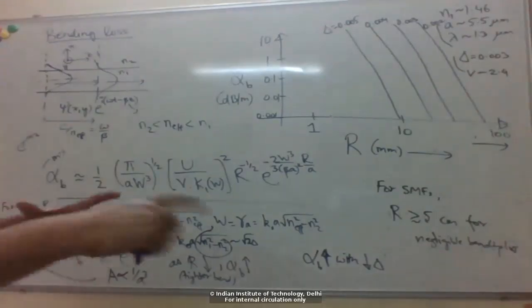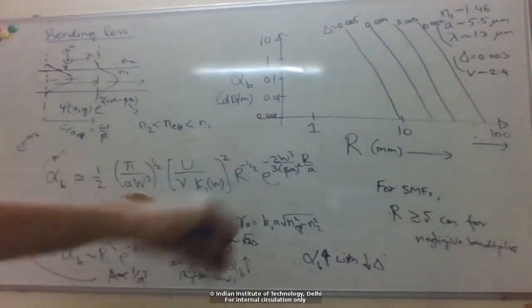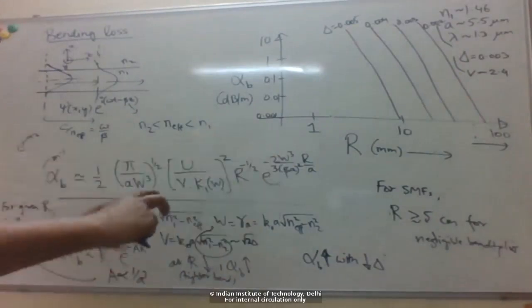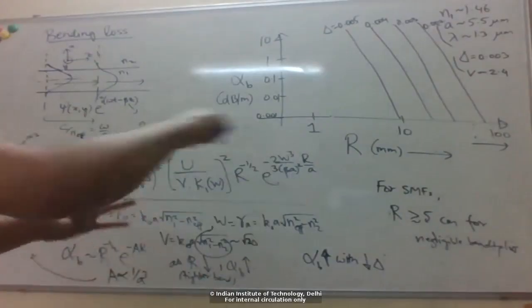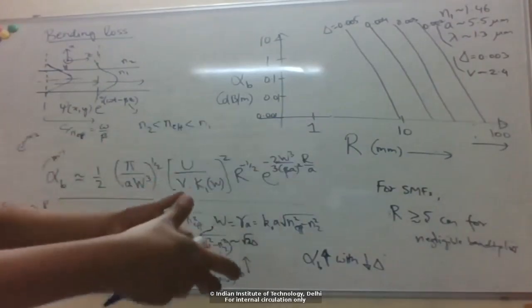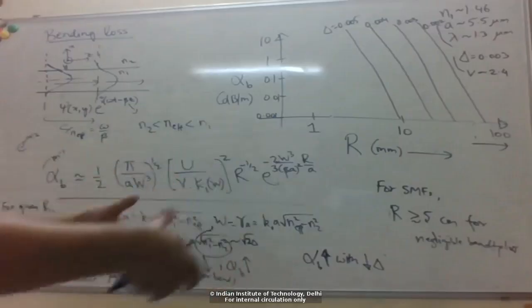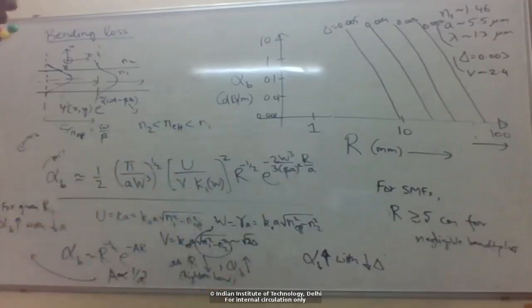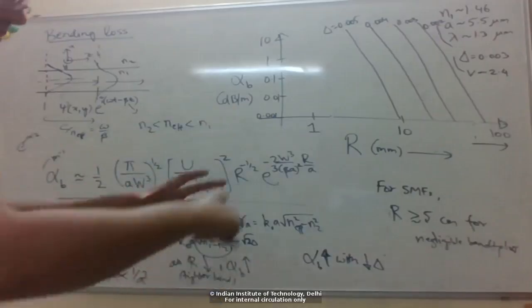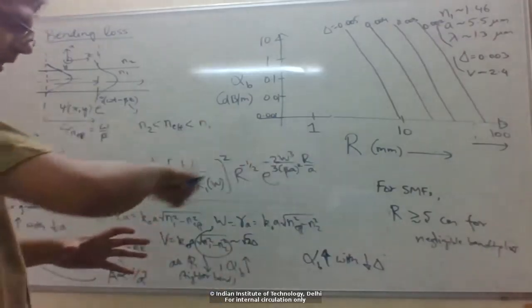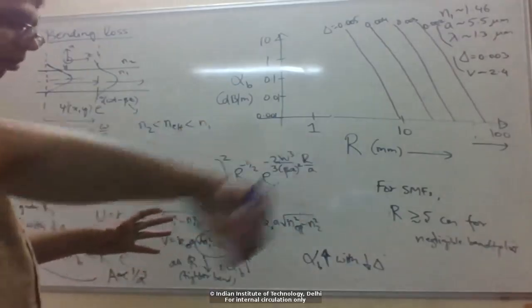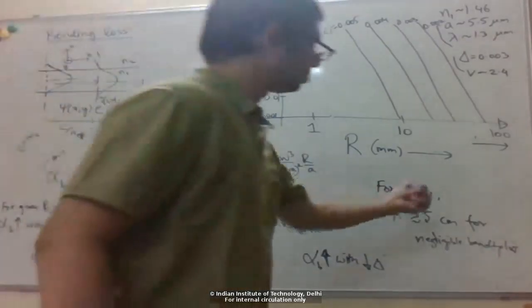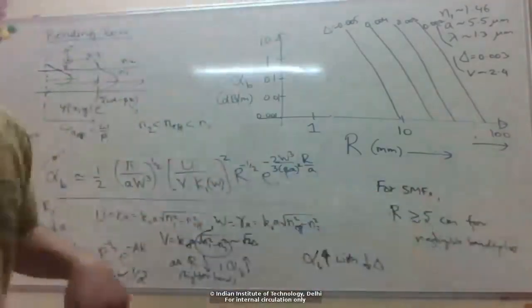Many times, for example, we also use fiber spools where the fiber is wound around a plastic spool, and you wind the fiber around many times. So you have, let's say, a kilometer length of fiber in just a small form factor, right? Then also the radius of the spool around which you bend the fiber has to be a minimum. Typically it's kept at 10 centimeters or more.